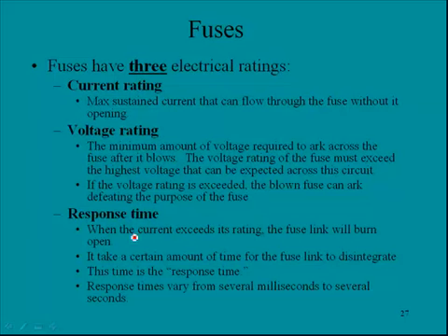Response time. When the current exceeds its rating, the fuse link will burn open. It takes a certain amount of time for the fuse link to disintegrate. This time is referred to as the response time. Response times vary from several milliseconds to several seconds, and due to the type of circuit, the response time will have to meet those needs. If you have real sensitive circuits, they need a fast response time. Not so sensitive circuits would not need a quick response time.